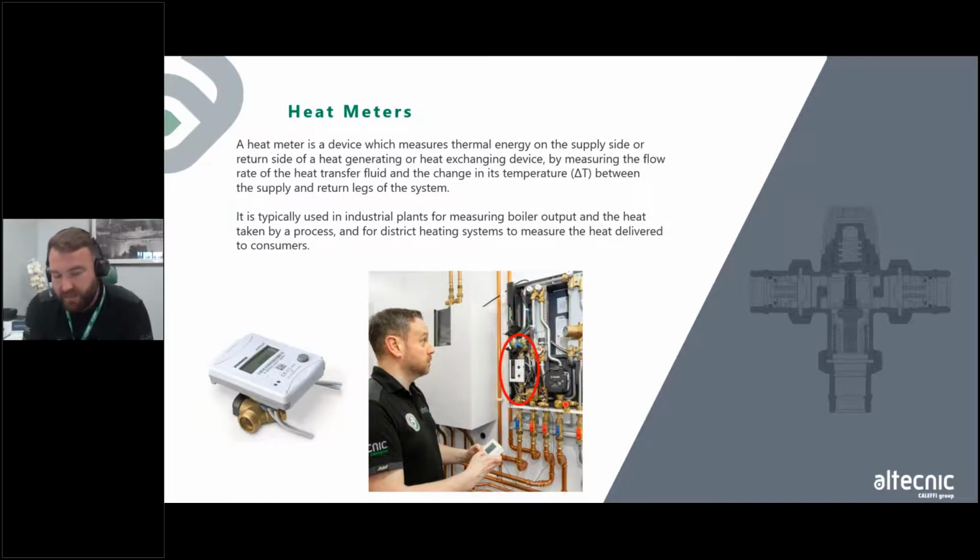So what we take in here is the equation. The way that a heat meter works is that we take the flow temperature that comes into the HIU, we take the return temperature that goes back out of the HIU, along with the flow rate, and that then allows us to calculate the amount of energy that's being used. It's vitally important that we have a big delta T.